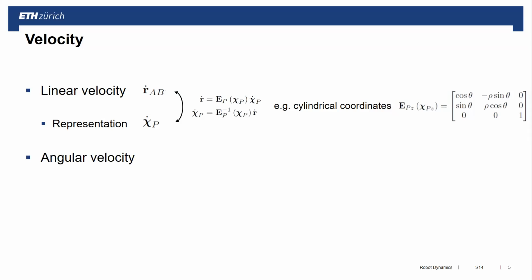Then we looked at angular velocities, the same thing there. Angular velocity first, so this omega, we showed that this skew-symmetric matrix of omega, which is given with this one, has a direct relationship to the time differentiation of the rotation matrix and the transpose of the rotation matrix.